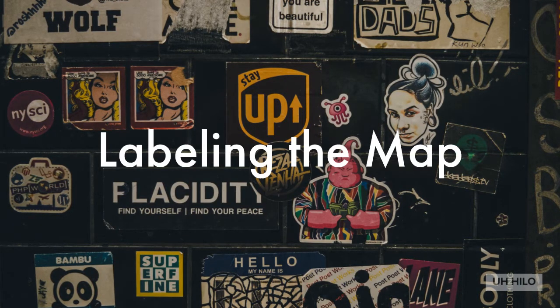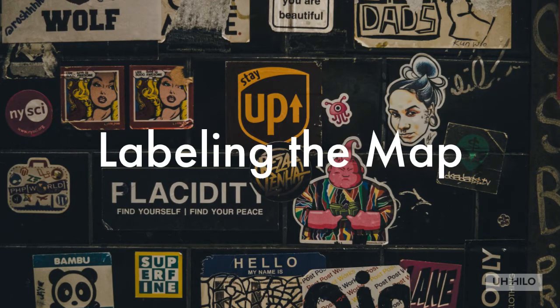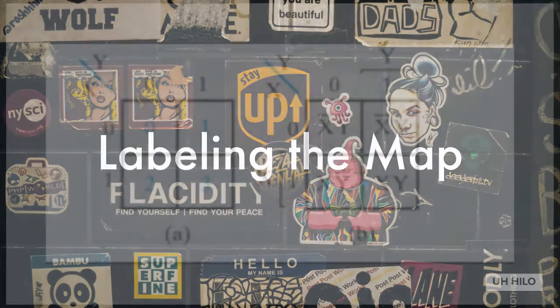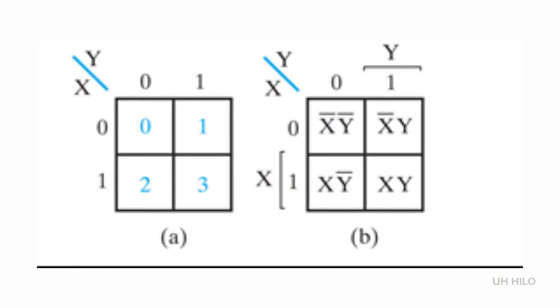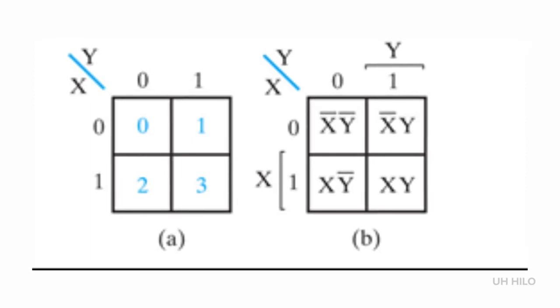Each location of the variable aligns with the region of the map for which the variable has a value of 1. This may be a bit confusing, so let's take a look at a concrete example, the 2 variable map structure. On the left, we can see where we can place each min term inside the 2 variable map structure, and on the right, we have the actual min terms in the cells of the 2 variable map structure.